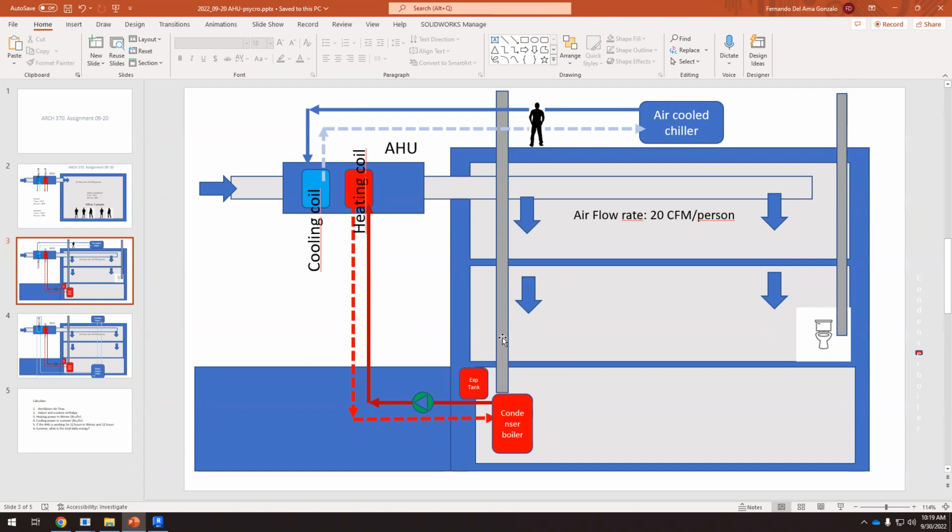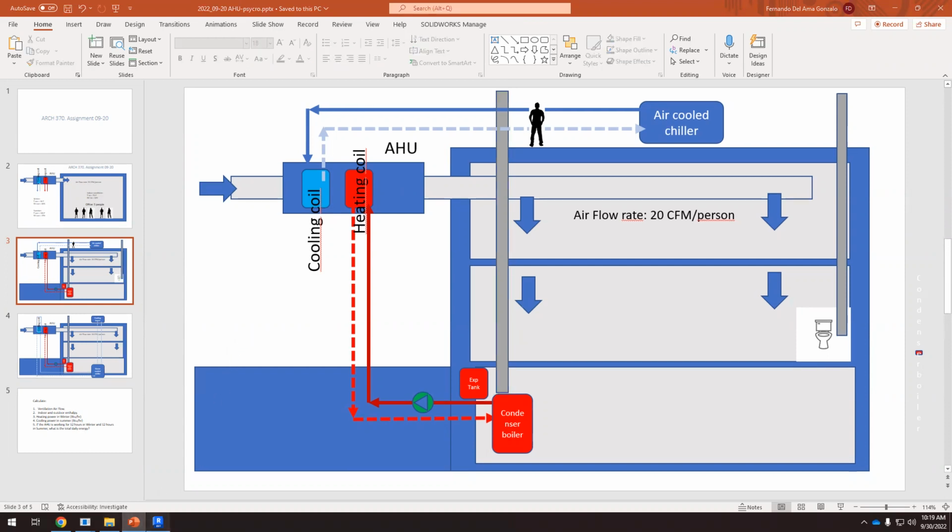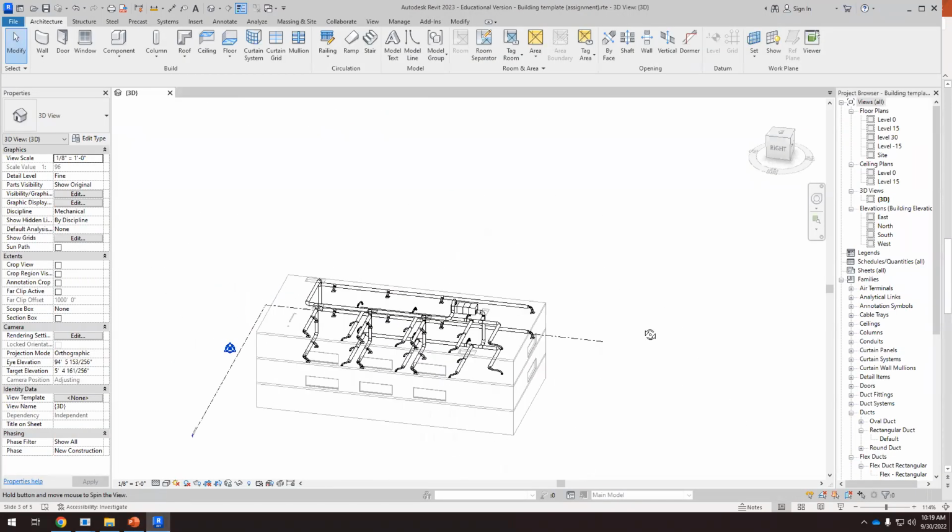And this pipe that goes out of the building, we have to reduce the size of the horizontal pipes. Okay, so it should be vertical. So we have to place this close to a shaft, so we minimize the horizontal part of this exhaust air duct. Though we have all those constraints, when we are analyzing the building, we have to keep that in mind. This is what we need, and now we look at our building and we see what we have to do.